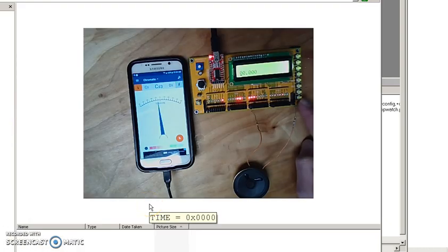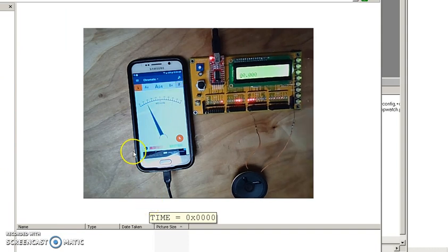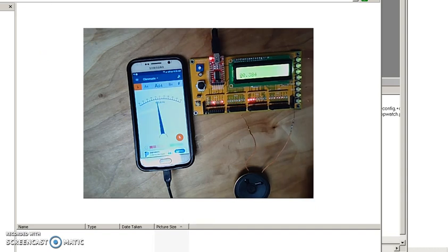I hit RB0, that starts the time. Hold on a sec. Sorry about that, I forgot to make port B input. I hit RB0, now the light turns on in port B. That turns on the stopwatch. RB1 turns it off. Stop. Start. Stop. Start. Stop. And RB2 clears. So now I have a stopwatch, good to 1 millisecond. That's a second use of timer 2, keeping track of time.